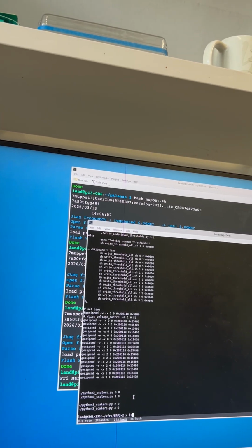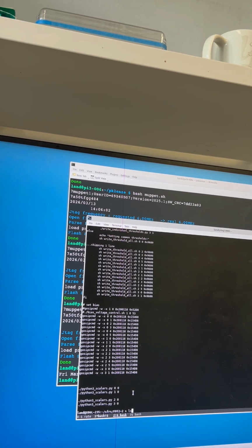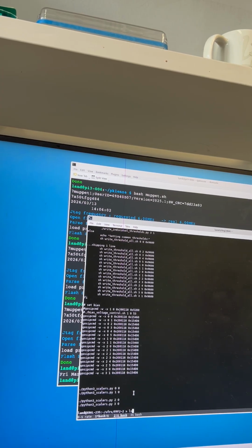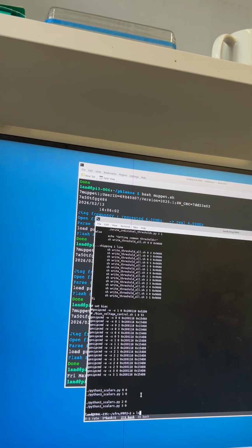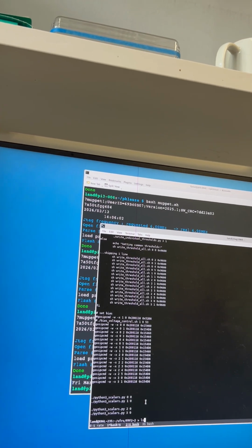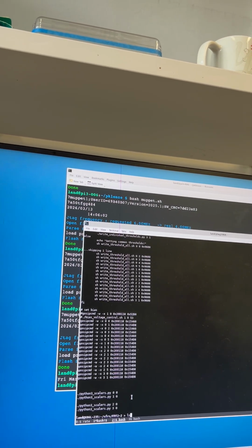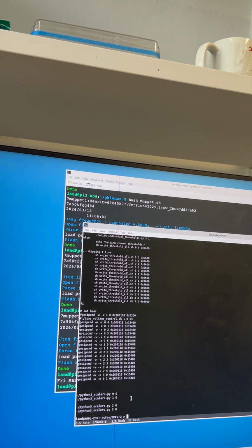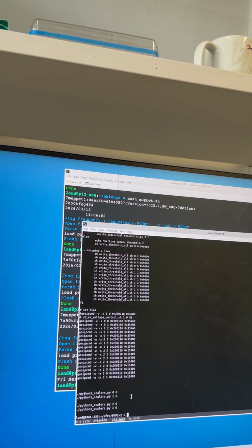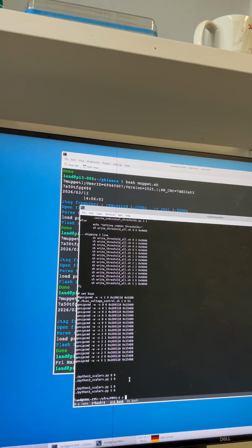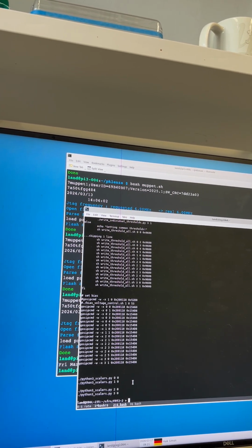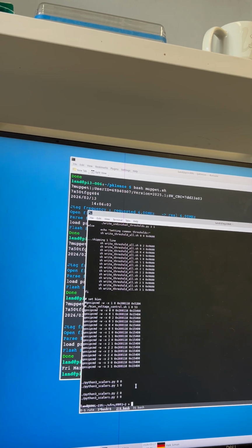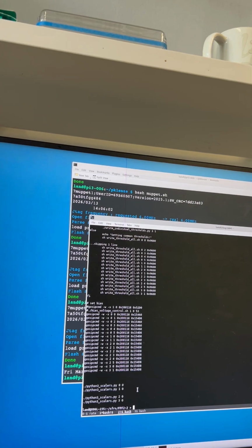All right. And so it takes a while after you set the voltage. It takes a while until you see the result. You need the ramping time. How many seconds? I think it's a minute or so until it has the bias. And then it stays always at this value. If it cannot reach the value, then probably you have a light leak, so that you have too much current, and then you cannot sustain the voltage.